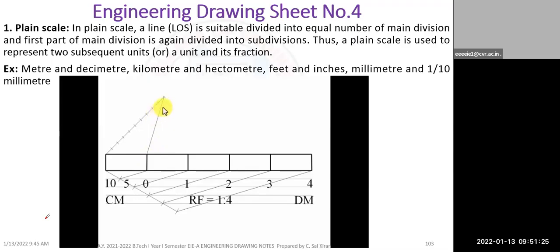Tighten the screw, move it to the ninth point, and then draw a line. You can clearly see that these two lines are absolutely parallel to each other. Keep on doing so from the eighth point, 7, 6, 5, 4, 3, 2, 1. That's it. You can clearly see that this line gets divided into 10 equal parts.